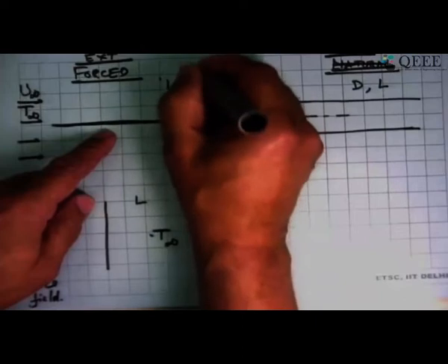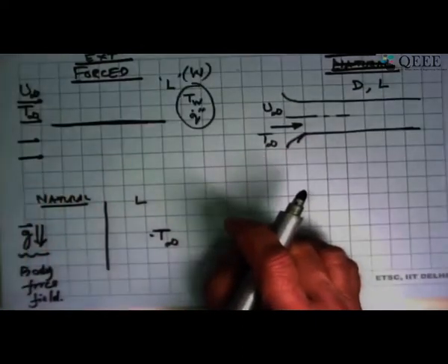It has a length L and fluid everywhere is maintained at T infinity. Here we say, okay, I now have more parameters in the problem. Geometrically, I have the diameter of this tube and the length of the tube to worry about. Here it is length, and normal to the paper is W, where we assume that there is no effect in the transverse direction. It's an assumption. In the real world, this too is not too well behaved.